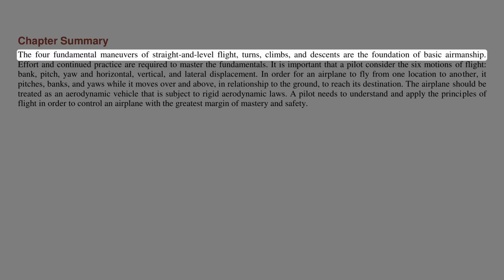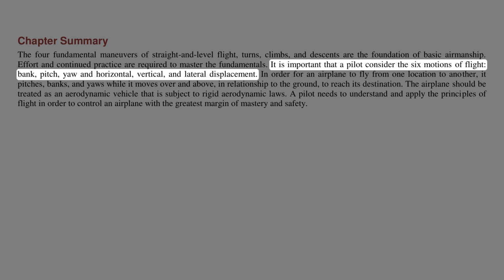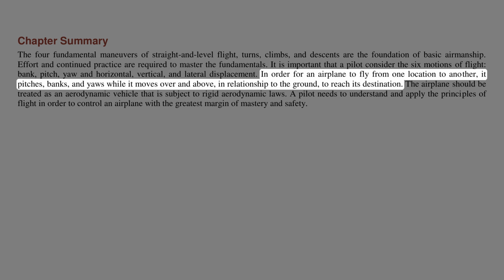Chapter Summary. The four fundamental maneuvers of straight and level flight, turns, climbs, and descents are the foundation of basic airmanship. Effort and continued practice are required to master the fundamentals. It is important that a pilot consider the 6 motions of flight: bank, pitch, yaw and horizontal, vertical, and lateral displacement. In order for an airplane to fly from one location to another, it pitches, banks, and yaws while it moves over and above, in relationship to the ground, to reach its destination.